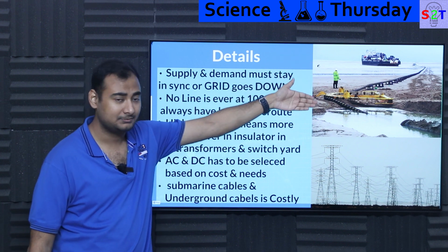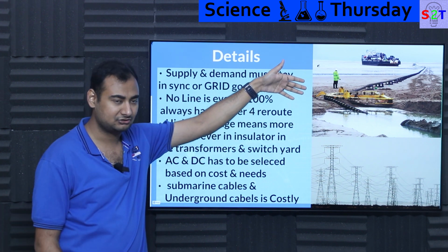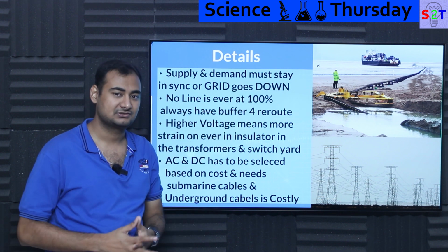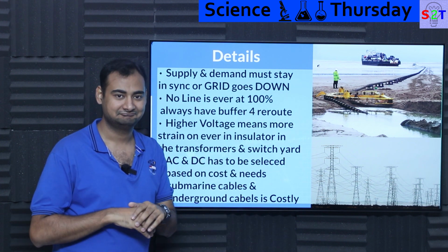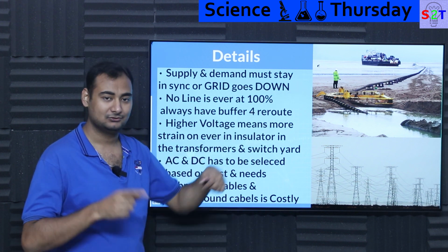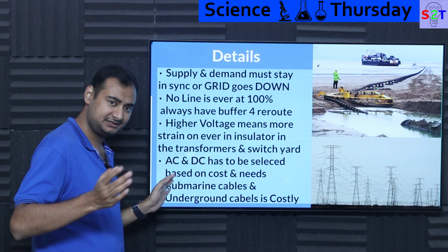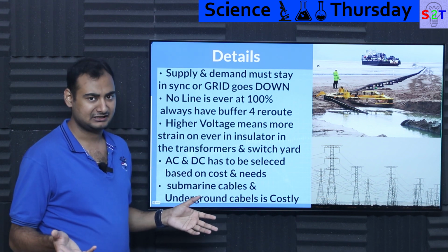And if you are like Europe and you are trying to connect all the nations, and many of the nations have to be jumped through sea, these things have to be high voltage DC. And high voltage DC also has this benefit that you can do monopole, meaning it's just one pole, done, go home. Like in AC you can have 3 poles, but here 1 pole is enough. So you have to choose. So AC cheaper, DC better. That's the whole point. You have to analyze the cost and the need.